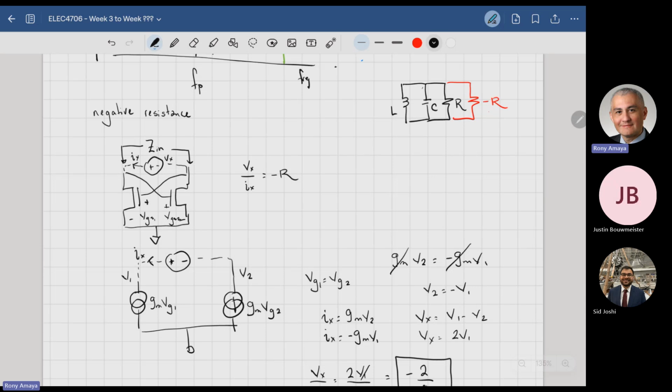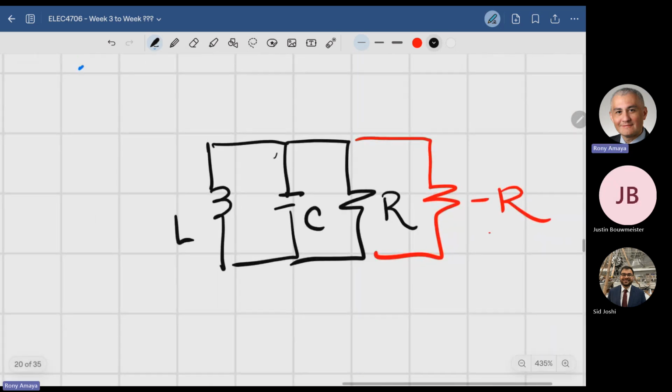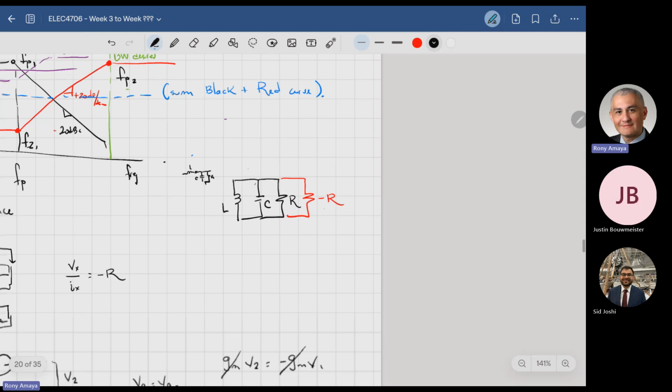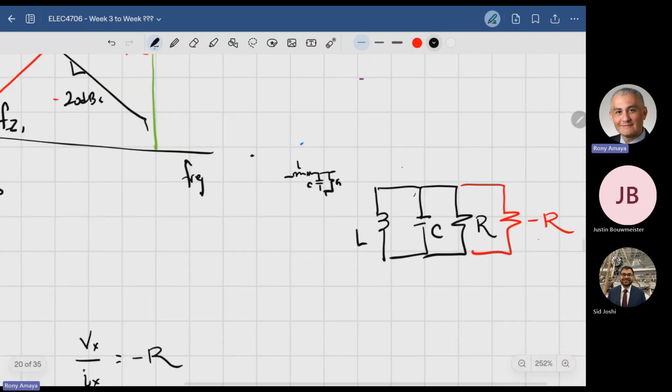So what this is all about, again, is the concept that you have a resonator, and I've drawn this in the top right corner, which is formed by an inductor and a capacitor, but it also has losses. And those losses are a function of the series loss. So you think about a transmission line, you've got the L, you've got the R, you've got the C, and then you've got the G, right? The actual series resistance, or R, is a function of the metallic losses in the circuit, and we also said that the G is a function of the dielectric losses. So it's a combination of all of those.